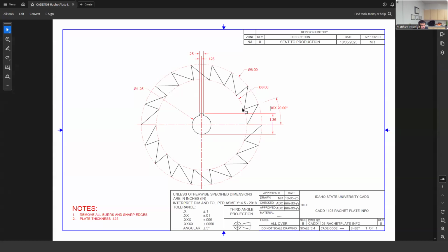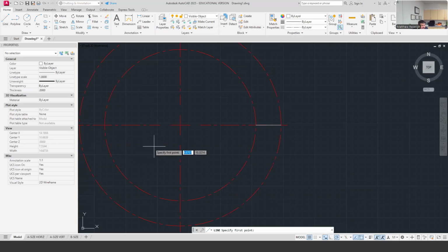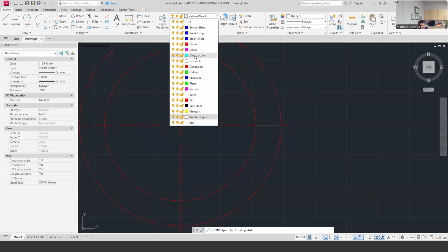So I might put that one in based off this one and draw this one. Maybe my first tooth that I'm going to complete and array is probably going to be this one right here, just based off what I've got. Or I could come 20 degrees down and stay with the one I'm doing. Maybe I'll do that. Either way, I'm going to have to come 20 degrees down and put another one in. It's the only other data I'm given here. And whether or not I array that, you could do that anyway. I can just do a temporary line here, a construction line, which I like.